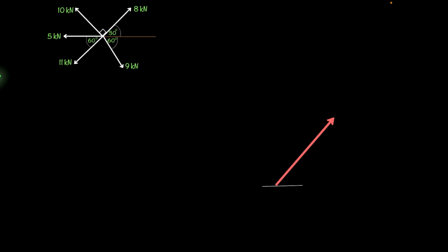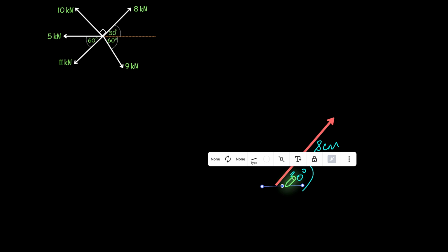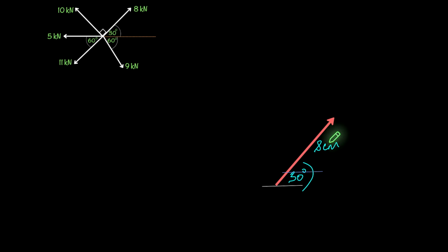Now, very crucially, the angle right here between the reference line must be the same as the angle between our 8 kilonewtons and that horizontal line there, which is 30 degrees. So right here, you should have 30 degrees. And let's say we were using centimeter measurements, this would be just 8 centimeters because we're using a 1-to-1 scale. Our next step would be to draw a reference line at the tip of the arrow that we have here. As you can see, I've just copied my horizontal reference line, placed it right at the tip of that arrow, and that's where I'll draw the next force.